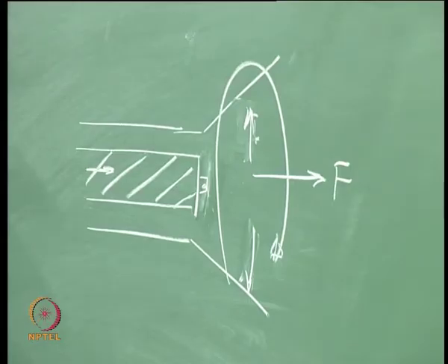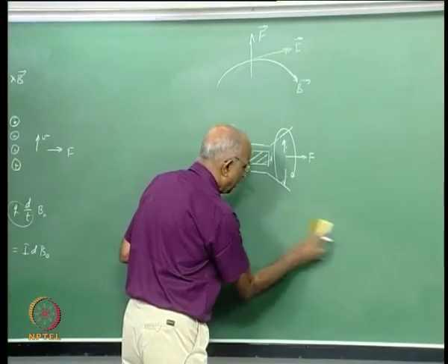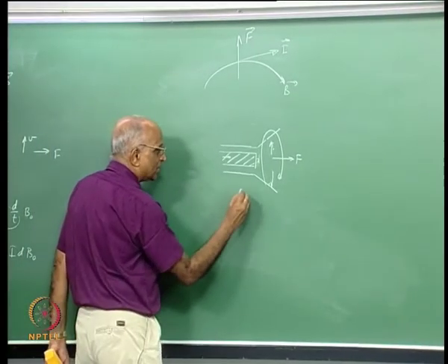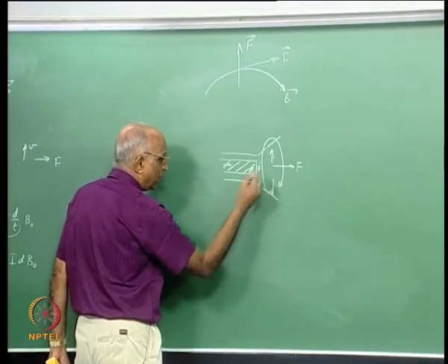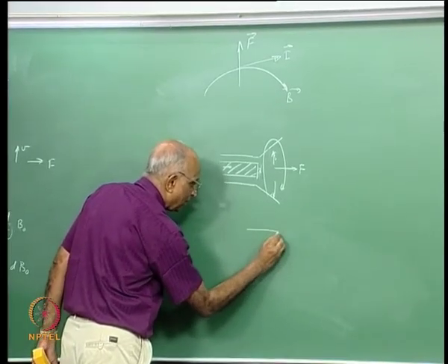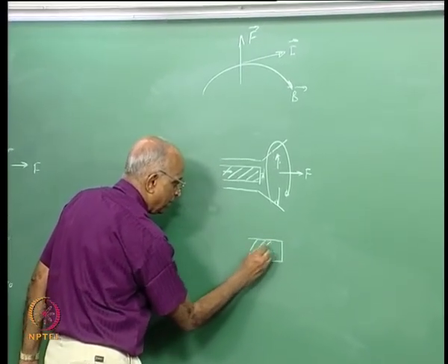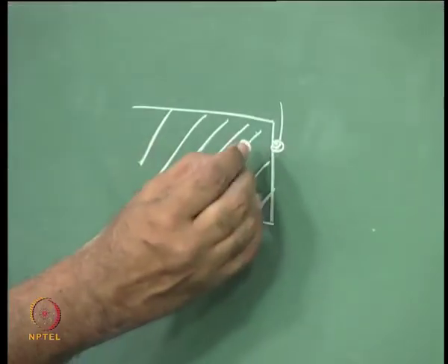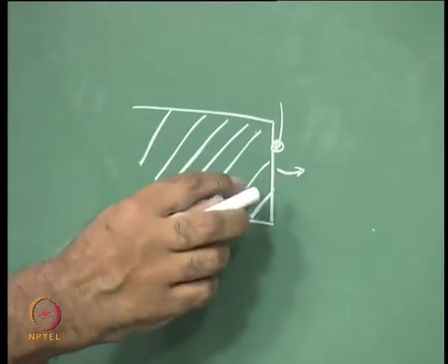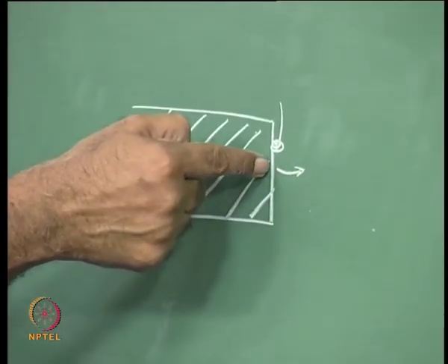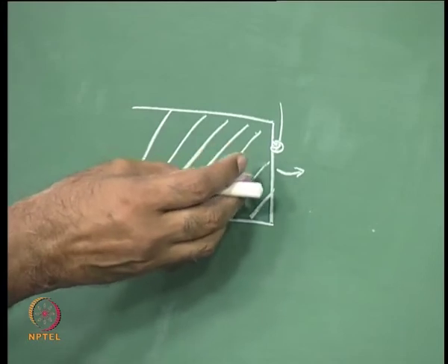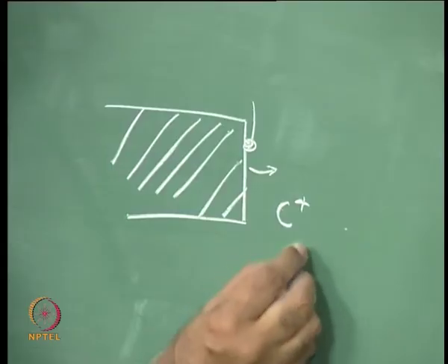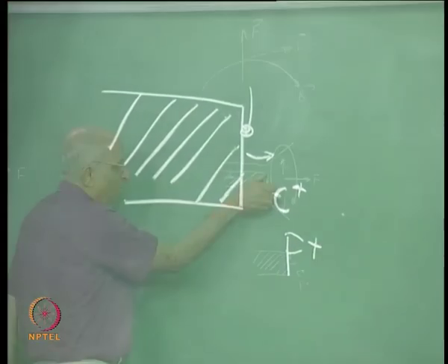One development which IIT Kanpur is working on is this: instead of having the thruster in this particular direction, why not have a material like Teflon, and I put an electrical spark here and therefore generate a plasma. When I have a material like Teflon, which is essentially carbon and fluorine, I generate carbon charges, I generate fluorine charges,